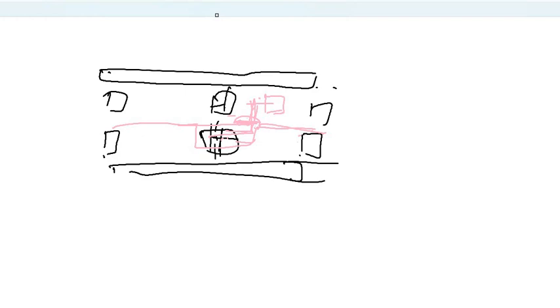To avoid this kind of routing congestion, we make a practice that all the even metals are horizontal, and odd metals are vertical. M1 has an exception because you have drain and source connections which are vertical, and some tiny local connections done using M1. If you end up drawing vertically, that will block the routing of other signals. So that's the reason we have this concept of alternating vertical and horizontal.